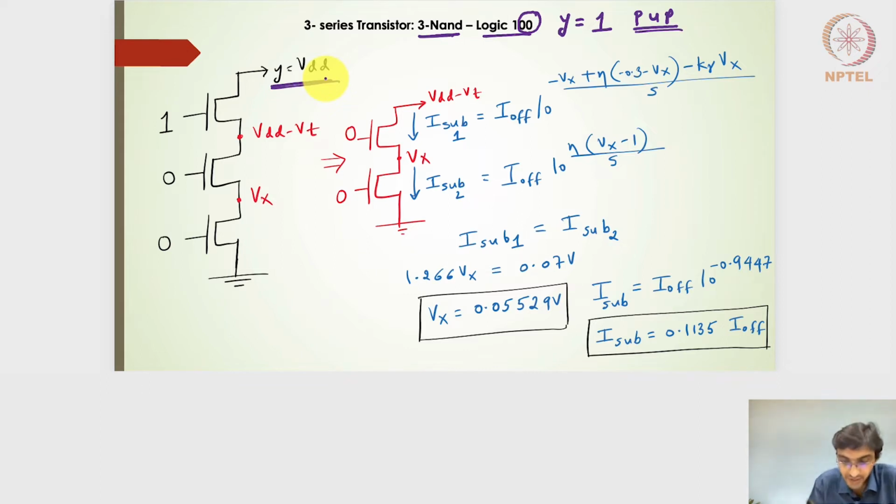So we know that when the transistors are getting an input of 0 0, especially for the NMOS transistor, these two transistors will be off, and the transistor with the logic of 1 will be on. If I consider this on transistor to be working as a pass transistor, where the drain terminal on one side is being charged to the VDD rail, then the other side can charge till VDD minus VT.